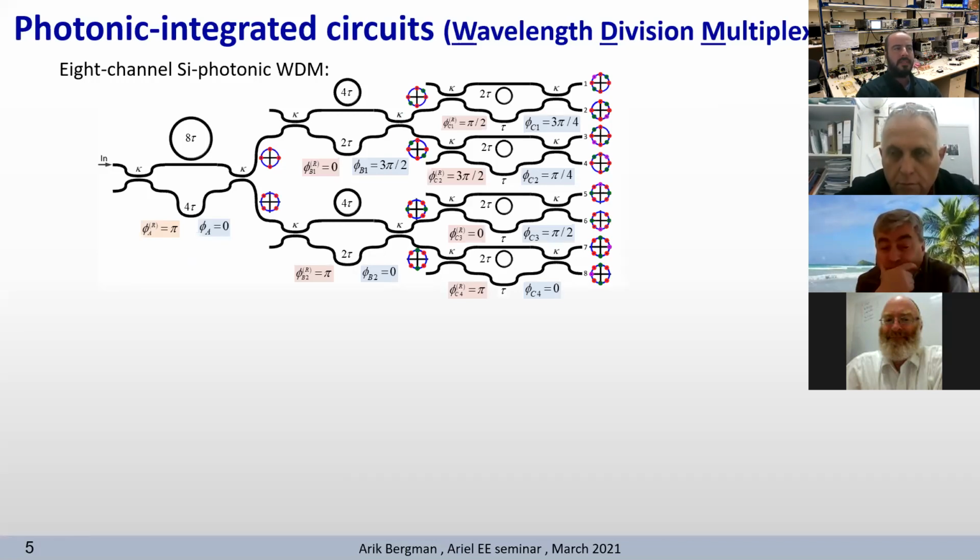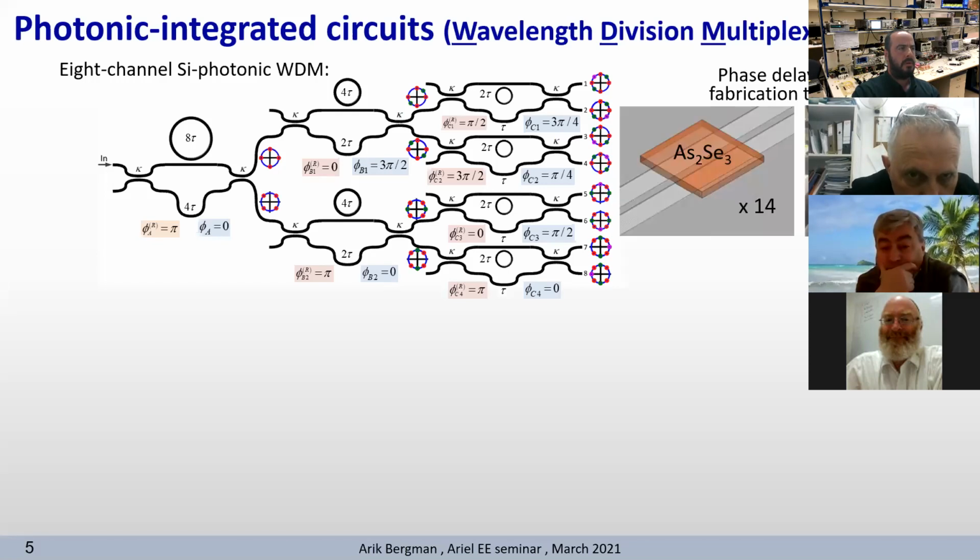In order to optimize the transfer function of these filters, we had to precisely control the optical phase delays of the interferometers' arms and ring circumferences. The required accuracies, however, cannot be achieved with fabrication tolerances of standard silicon photonic waveguide alone. To address this challenge, we used the following post-fabrication trimming technique.